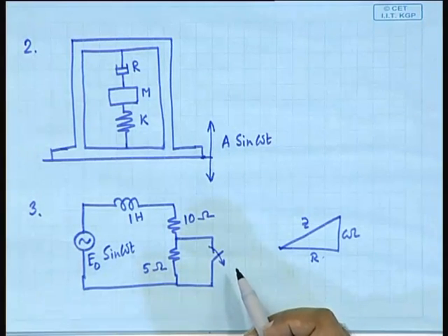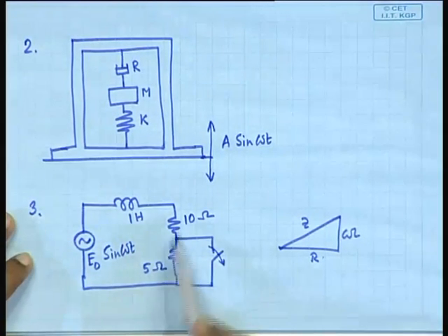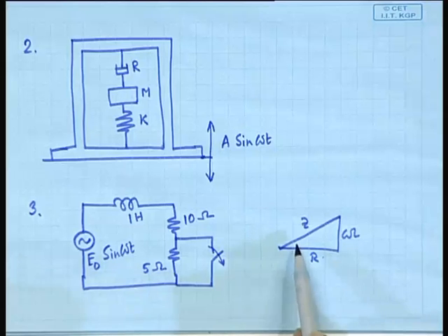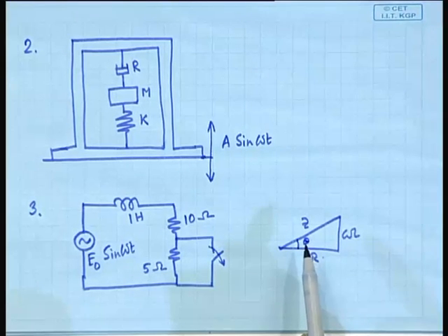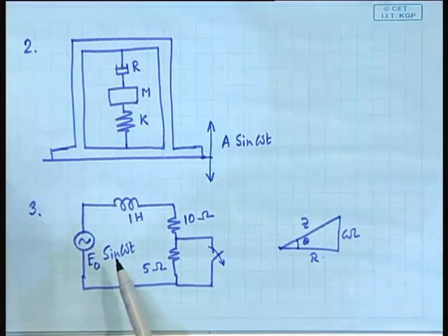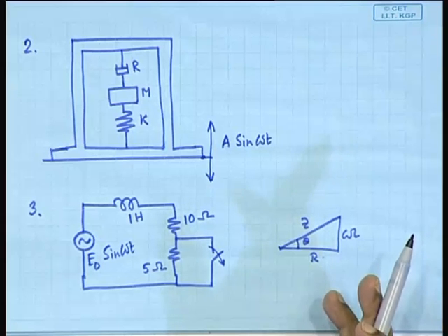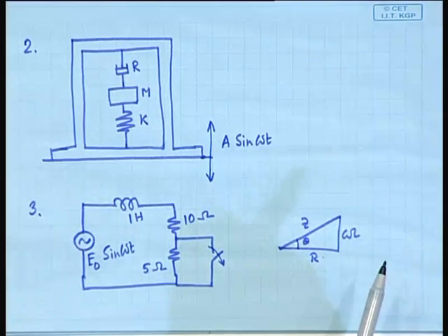We already know that you have to open it where the sinusoid is exactly at the right phase. If the new circuit, here it was 1 Henry, it will have a particular omega L. Now, the R is 15. For that circuit, whatever is the theta, if this one is opened at that phase angle, then only it will have no transient, else it will have transient. Okay.